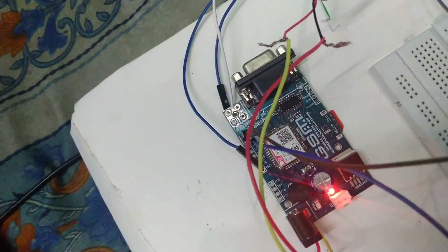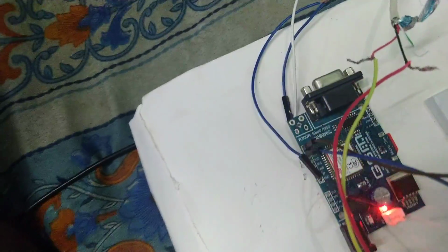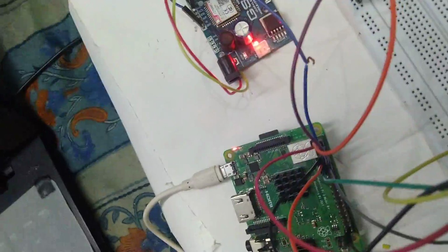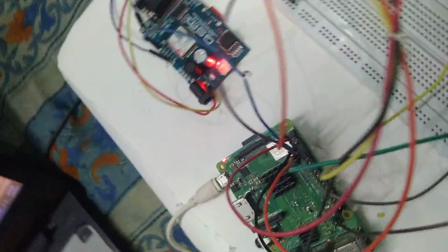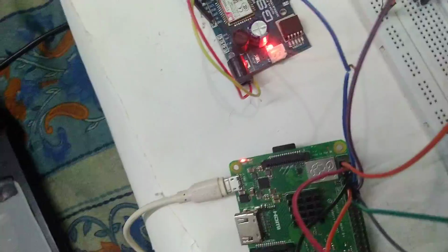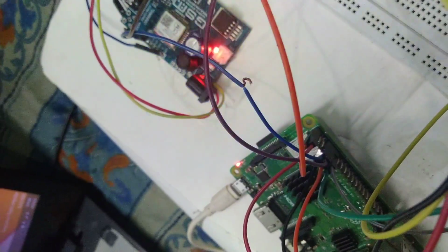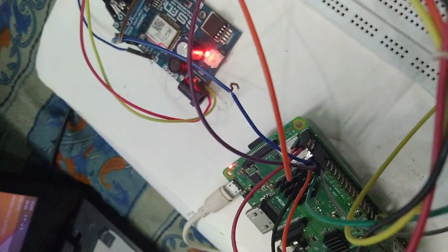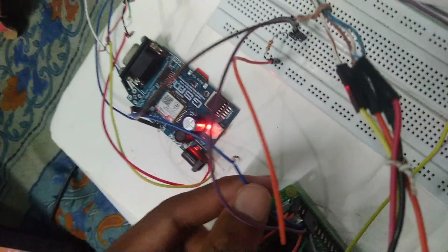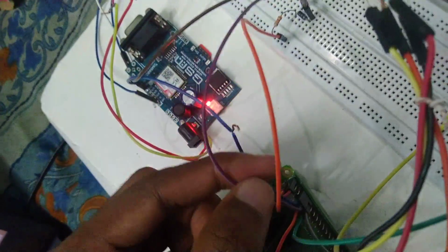As you can see, it is connected to the mobile adapter, and this is the SIM, one GSM SIM which we are using, and there are 3 inputs in this GSM which we need to give. One is RxD, one is TxD, another one is ground. And so coming to the Raspberry Pi, the RxD and TxD ports are number 4 and 5. As you can see from the right side, if we take these two lines as left and right, then from the right side the pin numbers 1, 2, 3, 4: 4 is TxD and 5 is RxD. So this TxD should be connected to the RxD of the GSM, and RxD should be connected to the TxD.